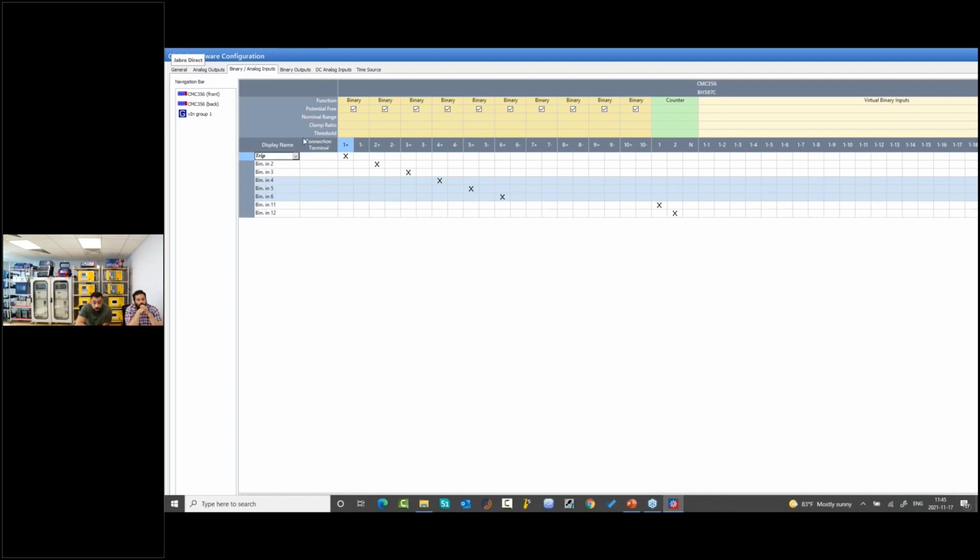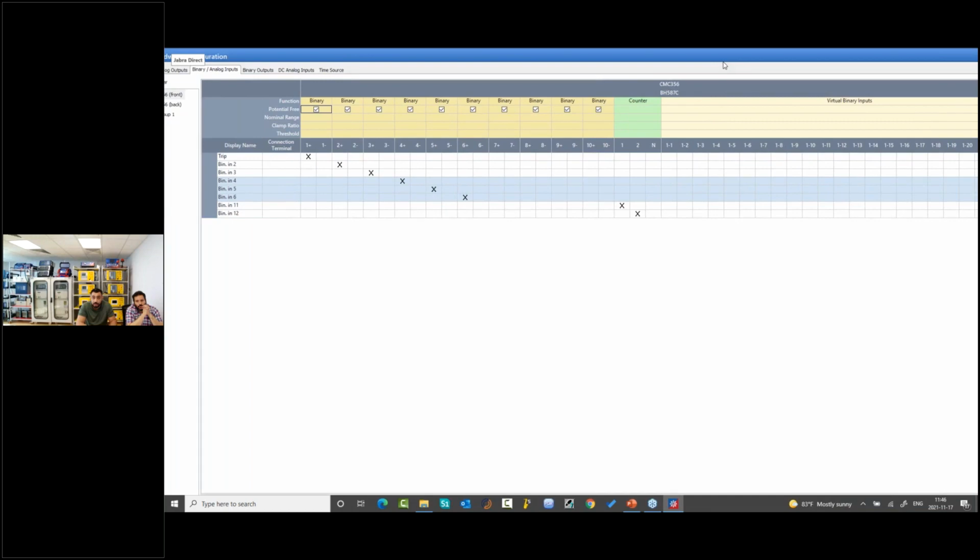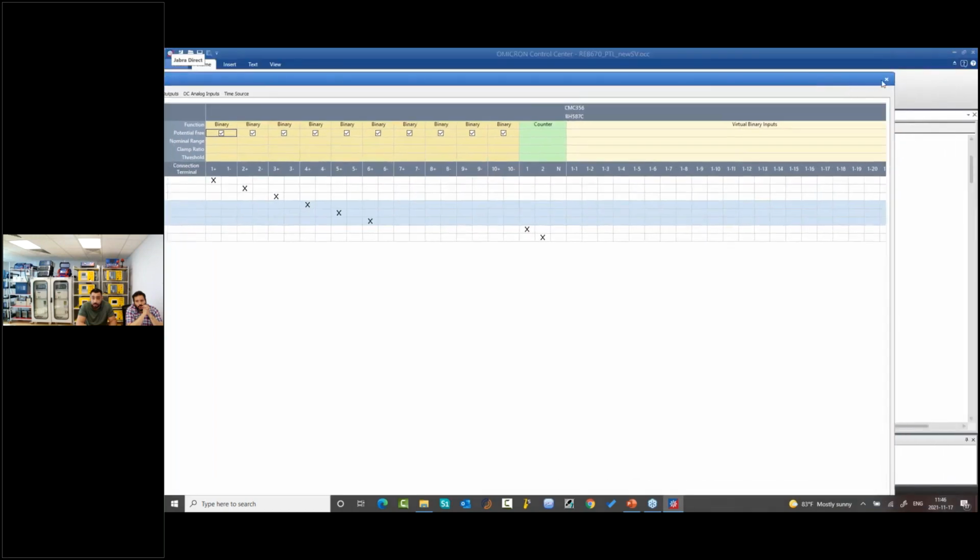But here, if I would like to have a wet contact or a dry contact, you can see it is here, which means it's potential free. If I would like to make it wet, I will remove it and enter the value of the rated voltage of my switchgear or substation. Then it will be multiplied by 0.7% to calculate the threshold to avoid any operation in case we have an earth fault in the DC system. We didn't change it, so we will save.